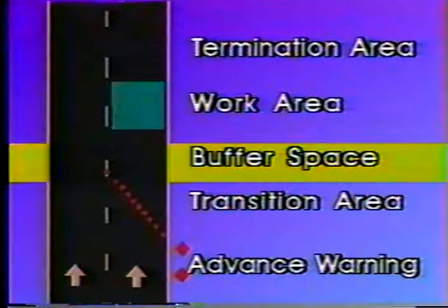If space allows, a buffer area comes after the transition area. This is simply a recovery space for drivers who fail to make the transition from the closed lane. In keeping with the principles we discussed earlier, it's important to keep this area clear of construction equipment and materials.